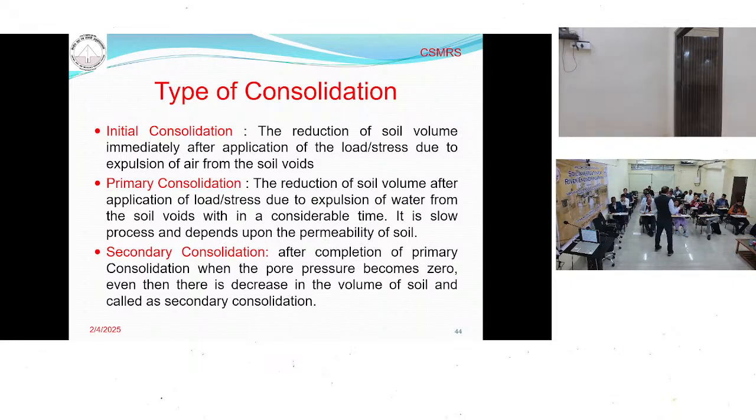When we talk about soil, we see the soil particles as interconnected. Between the soil particles there is a quite viscous liquid. Due to the load, some of the viscous water will come out and the particles come closer. In that way, secondary consolidation takes place.